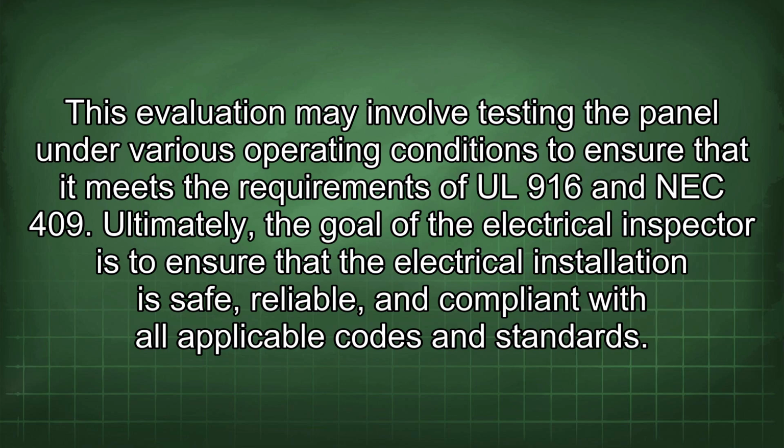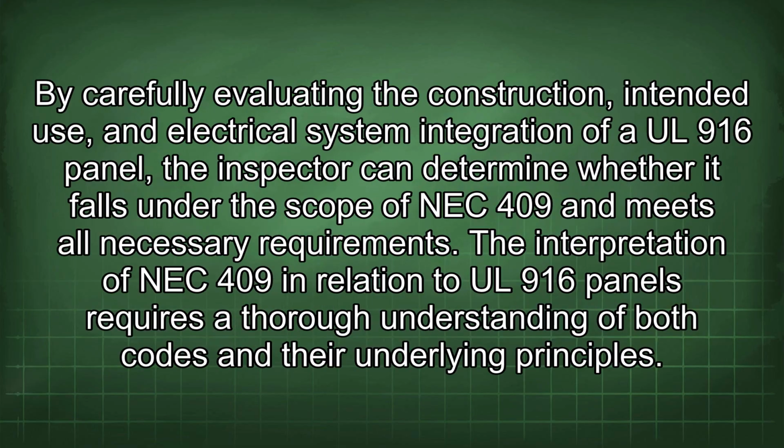Ultimately, the goal of the electrical inspector is to ensure that the electrical installation is safe, reliable, and compliant with all applicable codes and standards. By carefully evaluating the construction, intended use, and electrical system integration of a UL 916 panel, the inspector can determine whether it falls under the scope of NEC 409 and meets all necessary requirements.